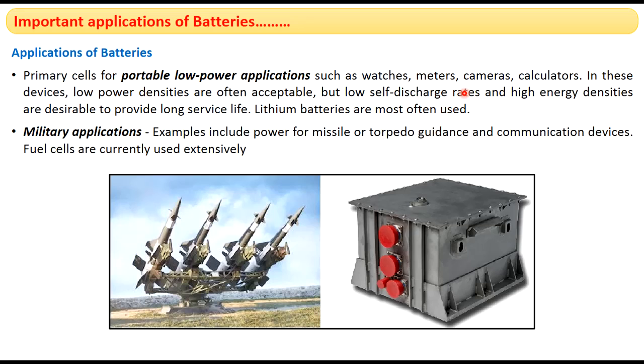Long service life is also required. The best example is lithium batteries, which are mostly used for this type of application. So primary batteries used for portable low power applications should have low discharge rate, low power density, high energy density, and long service life.